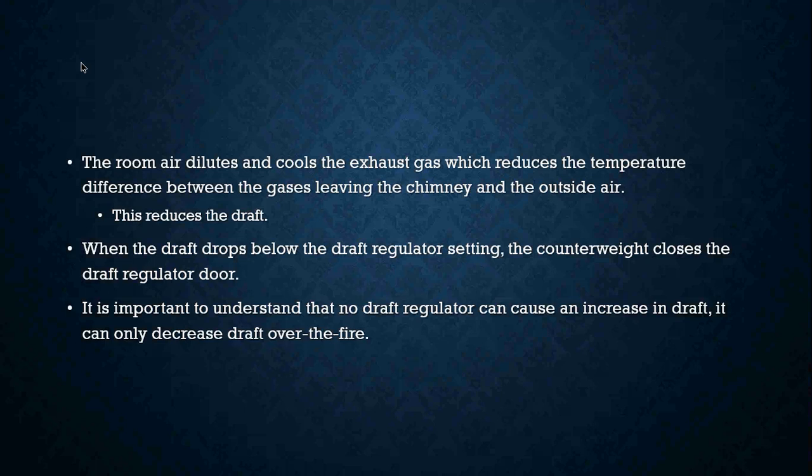When the draft drops below the regulator setting, the counterweight closes the draft regulator door. It is important to understand that no draft regulator can cause an increase in draft. It can only decrease draft over the fire. That is so important when it comes to dealing with draft regulators, understanding what it does.